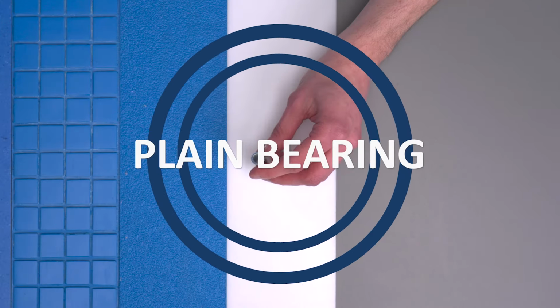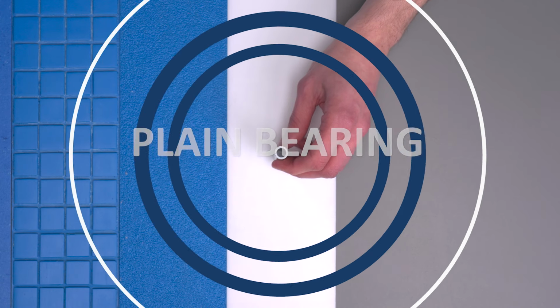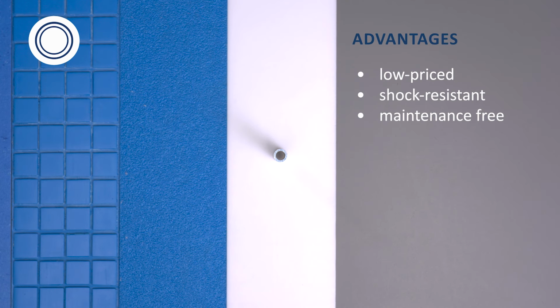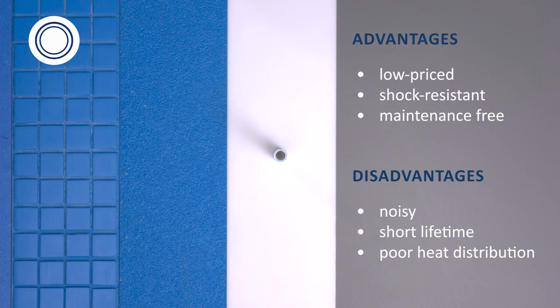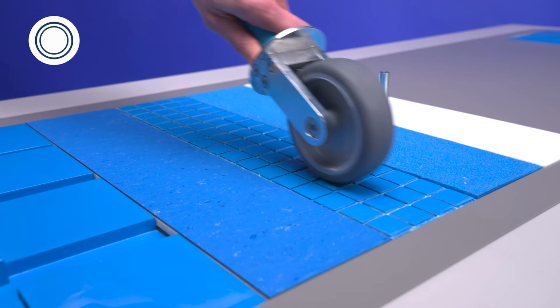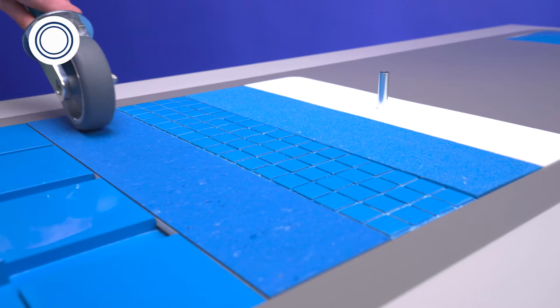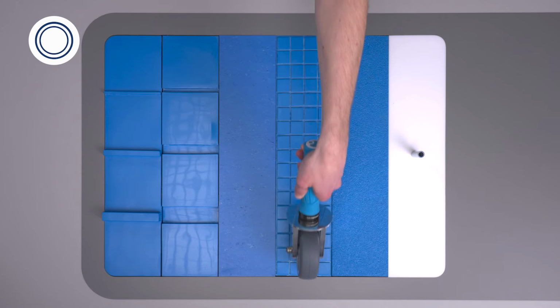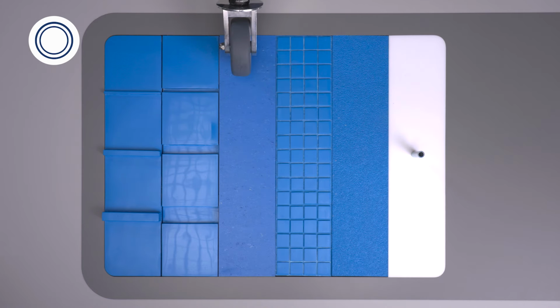The plain bearing is the basic form of wheel bearings. This type of bearing is low-priced, shock-resistant, and maintenance-free, but they are also noisy and have a short lifetime. The parts that move relative to each other are always in direct contact. That's why they are recommended for low speeds and short distances, because in constant use, hot running problems can come up.